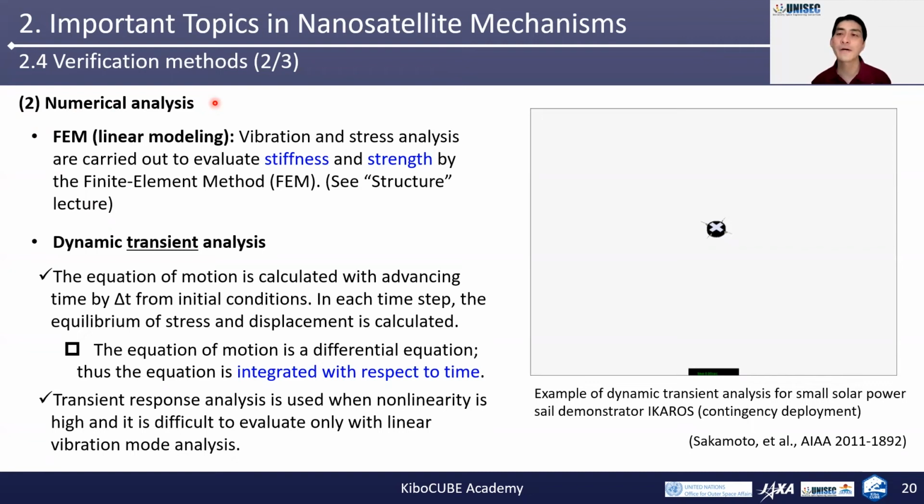Second, I will talk about numerical analysis as a verification method, especially for deployable structures. So linear modeling in the finite element method is often used. Modal vibration analysis and stress analysis are carried out to evaluate the stiffness and strength of the structures. Please see lecture 11, structure lecture.